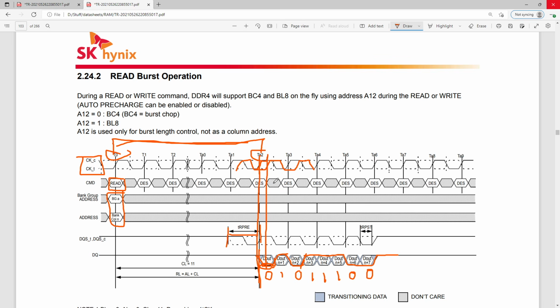And theoretically you could also have a memory controller that just uses a fixed delay relative to the clock signal, but I would assume that's probably way more complicated to do than to just have a second clock, a read clock signal that's 90 degrees out of phase with the main clock signal that you have. Anyway, that's how double data rate is possible.